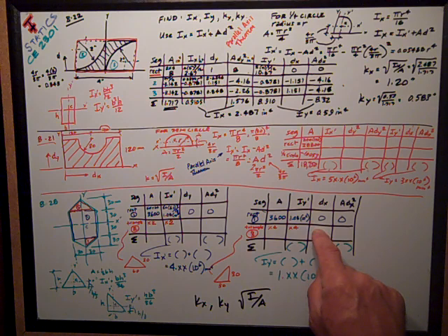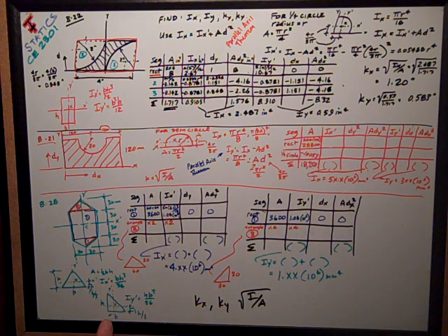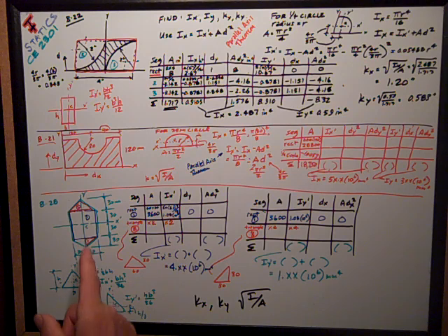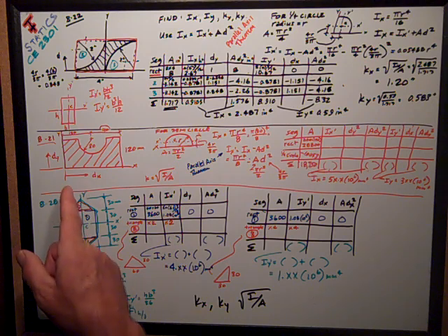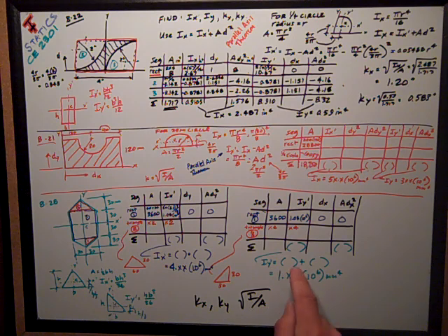The dx distance is going to be this 1/3, actually in this case b, it's the same number, from the centroid of it to the y centroid axis of the overall composite section. Square it, sum those. Iy is equal to that column plus that column, which is 1 point something something times 10 to the 6th millimeters to the fourth.